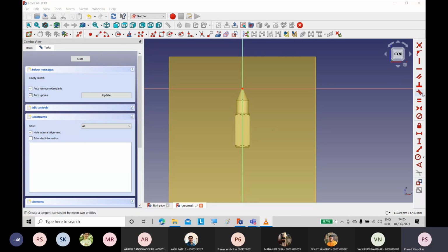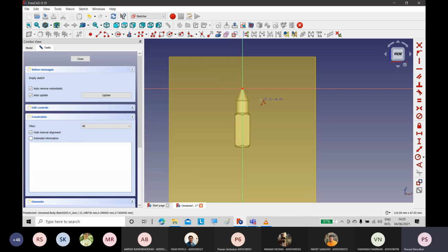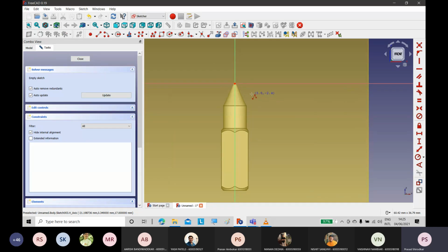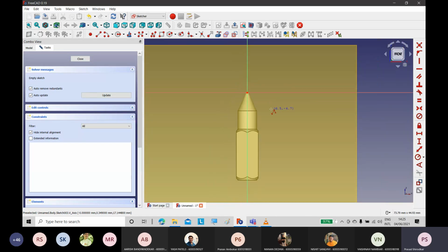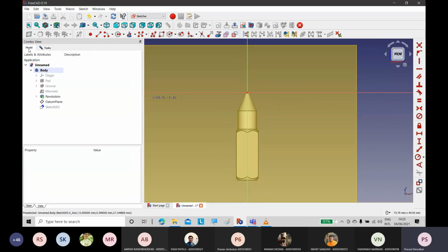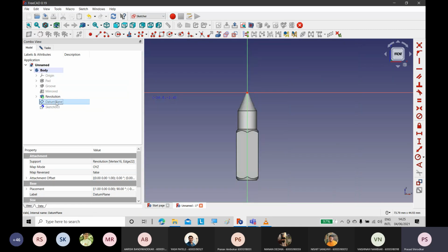Okay. So select the polyline option, and now you need to. So now, if the datum plane is creating any clutter, you can go to model and just switch off the datum plane. Okay, so as we don't need the datum plane, we are already sketching on the datum plane. Once we set it, you can remove it. Okay, so select this, draw this, construct this polyline and construct it in a similar manner.